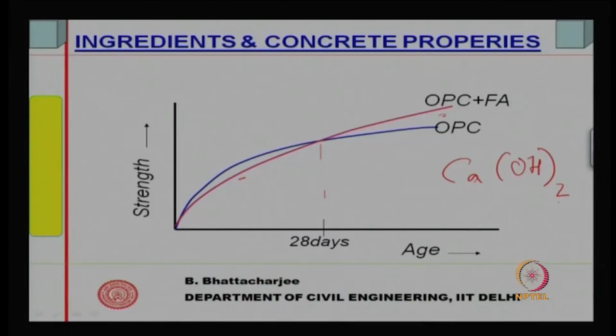So, this indicates that whereas in a cement water system you can simply demold it after 24 hours, here for 48 hours you do not demold and you do not test for strength. A cement system you can test for strength even after 24 hours or 3 days, but here you test it only after 8 days. Since you test it only after 8 days, it shows that the reaction process is very slow. That is one effect. So, A, reaction rate is slow.